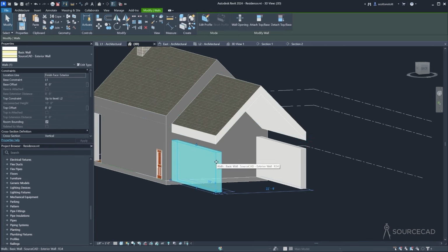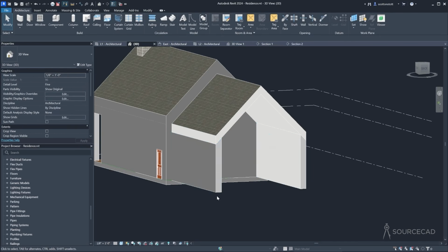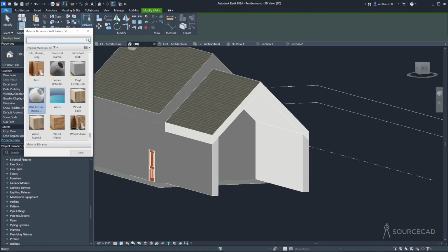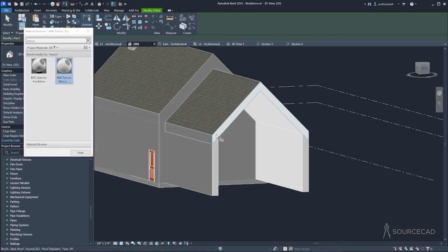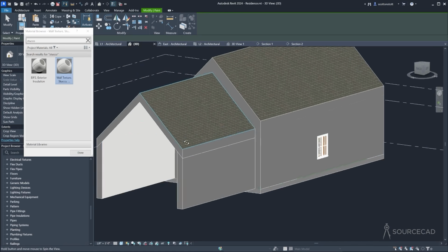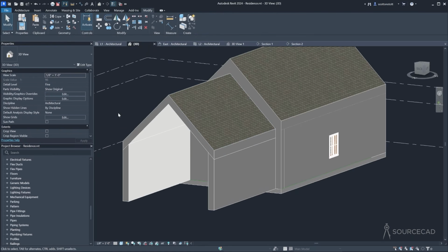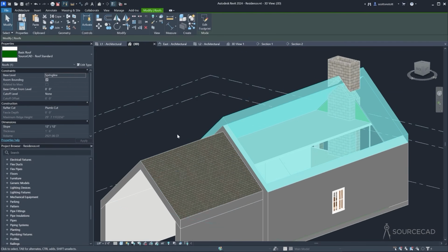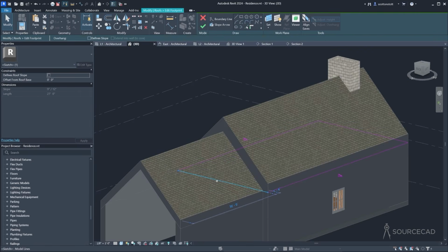And then I want these walls to go up and meet the roof. So I'll select them and attach them to the roof, like so. And then, as before, I don't want to see the gypsum board on the outside. So I will paint them stucco on these surfaces. Next, I would like this roof to project beyond the wall slightly. I think this will be an interesting detail. I'll edit the footprint of the roof and just pull this out 7 feet and see what happens.